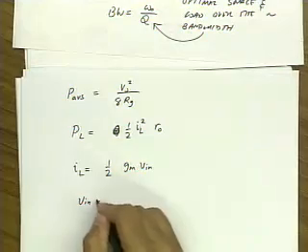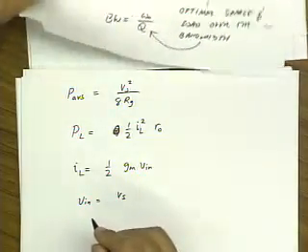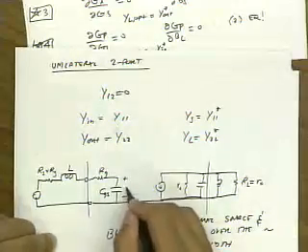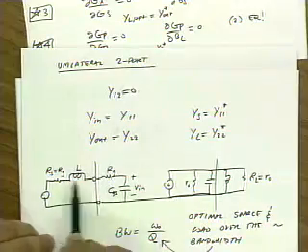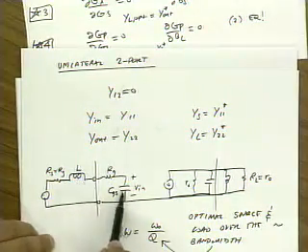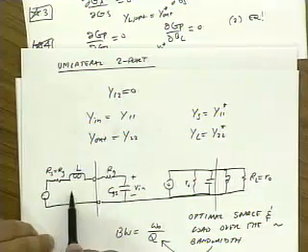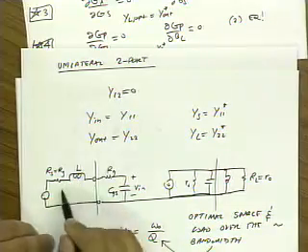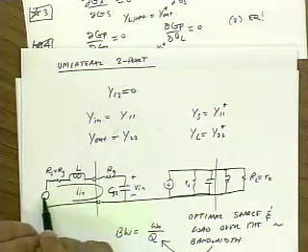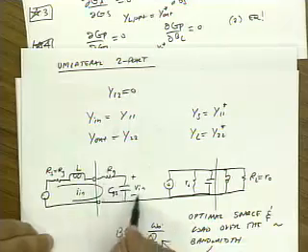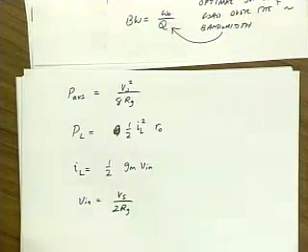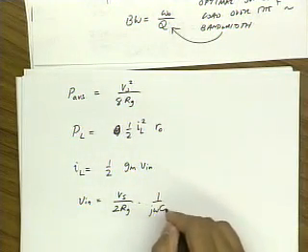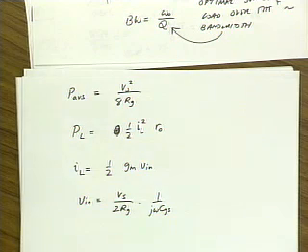Well, V in, it's a series resonant network. So V in, which is here, is equal to this voltage divided by this series RLC impedance. Well, again, at resonance, this cancels out with this. So V in is this current flowing in this loop, I in, which is simply Vs divided by 2Rg times this reactance. So V in is Vs divided by 2Rg, that's the current, times 1 over j omega CGS. Okay? That clear? Good.